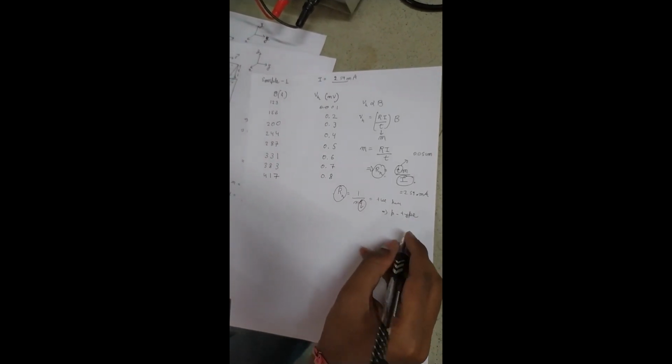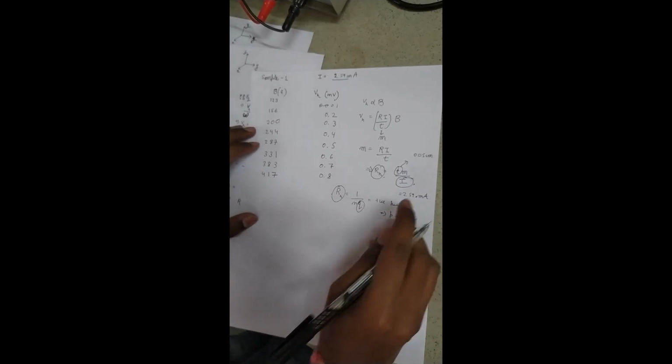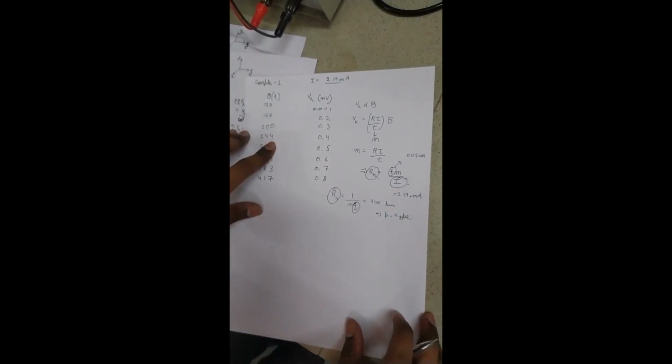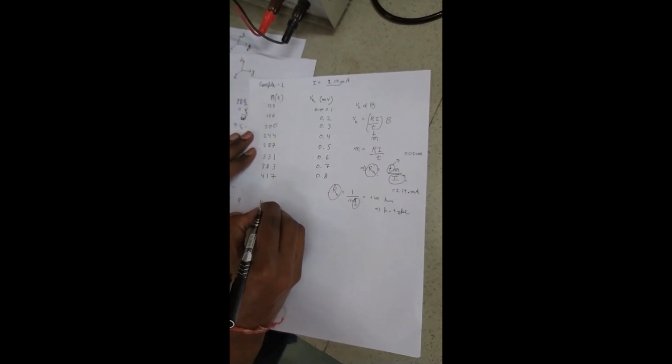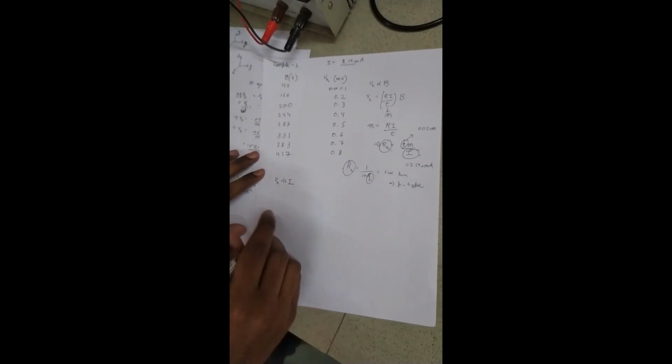The sample which we have provided was a germanium semiconductor. So we can conclude that the germanium sample provided here was doped with p-type material. So that's the first part. The second part is plotting a variation of VH versus the current, which we can also do here.